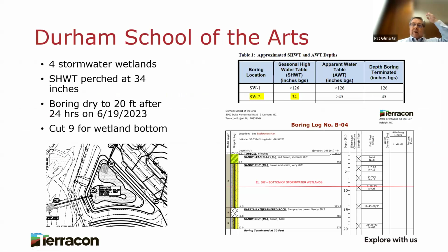Talked a little bit about Durham School of the Arts. This project is going to include 4 stormwater wetlands for stormwater management. Terracon performed soil science hand auger borings to evaluate the seasonal high water table in addition to the geotechnical borings. I sent the soil scientist out there.